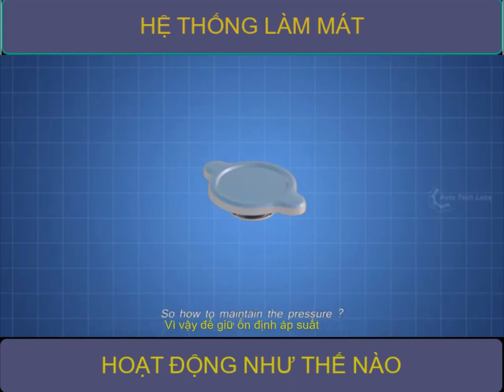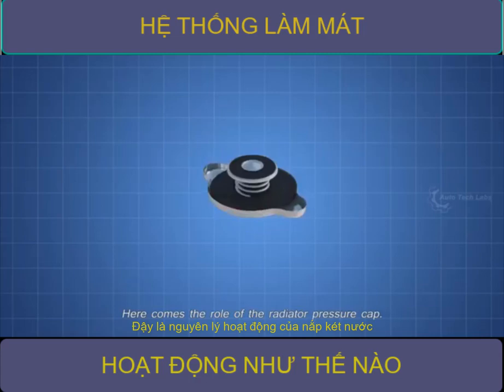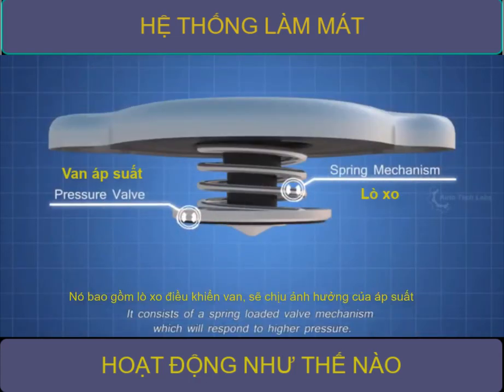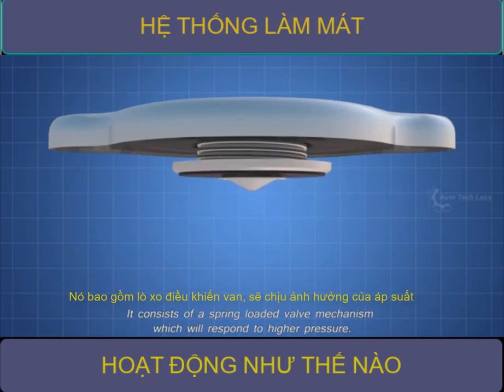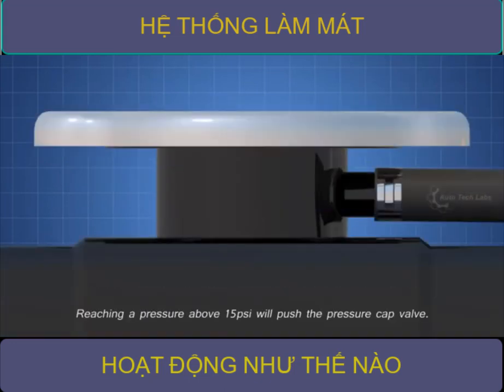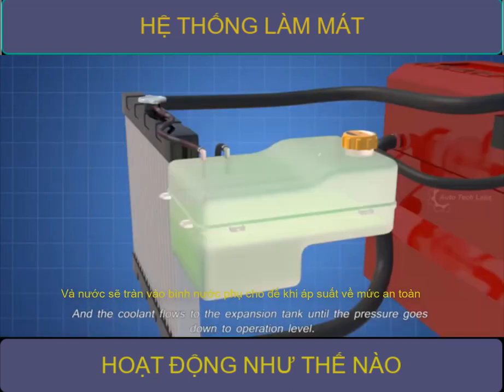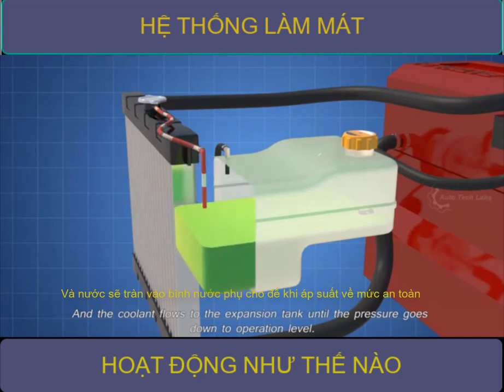Heating liquid inside a closed system always builds up pressure. So, how to maintain the pressure? Here comes the role of the radiator pressure cap. It consists of a spring-loaded valve mechanism, which will respond to higher pressure. Reaching a pressure above 15 psi will push the pressure cap valve, and the coolant flows to the expansion tank, until the pressure goes down to operation level.